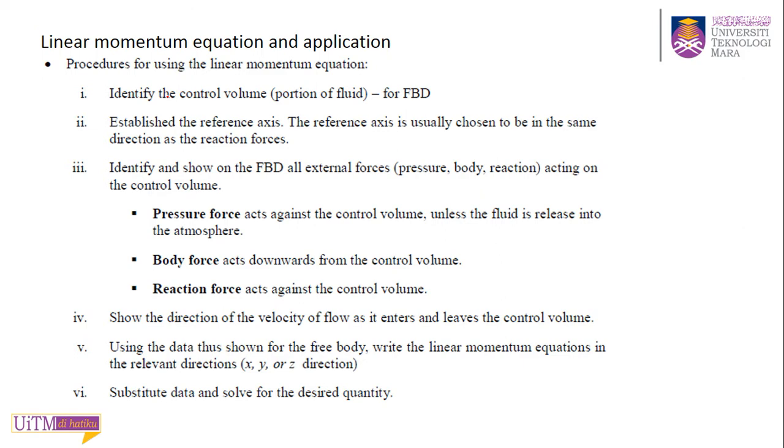And the pressure force P times A acts against the control volume, unless the fluid is released into the atmosphere. So the pressure force is P times A, and the body force is W, the weight. If they give you the weight of that pipe or the fluid has some weight, you need to consider this force, the weight.